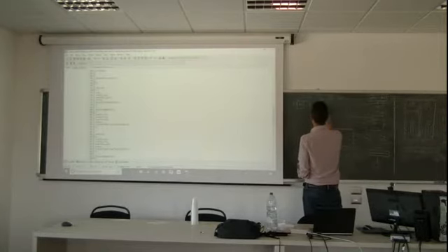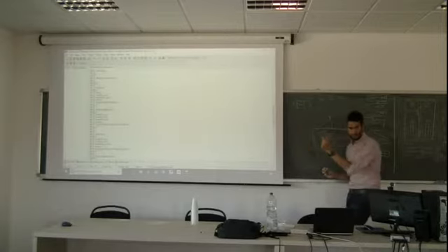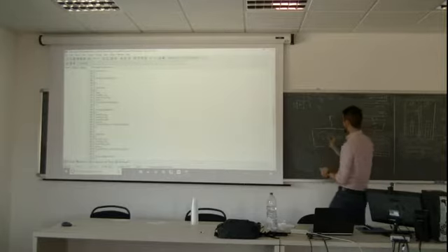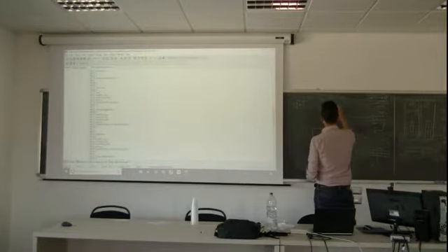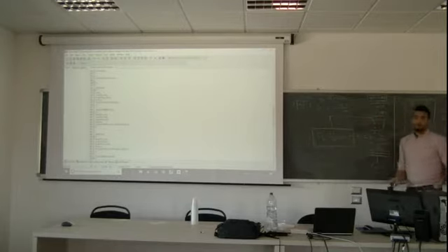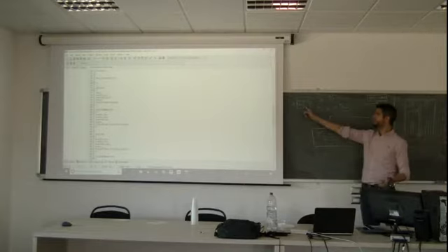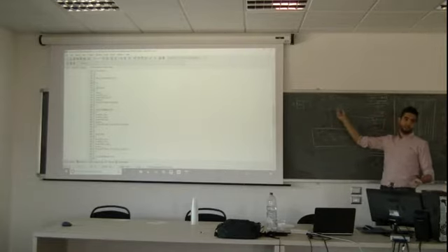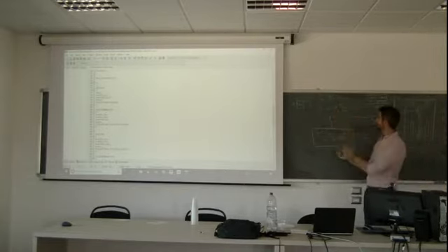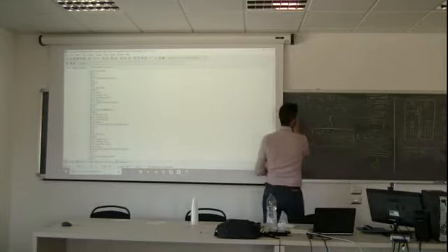So this is QB, it's 500 multiplied by the volume. The volume is delta x1 divided by 2 because it's half the thickness, because it's at the edge. Multiplied by QB plus K times (TE minus TP) divided by delta x1. Right? Applying Fourier, because it's negative, it's leaving the node. Negative because it's minus K, it's plus. Okay, now we isolate TP here.